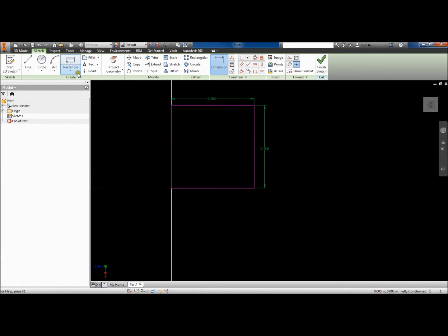The advantage of using the rectangle tool is that if you look at these different pieces, they're already constrained, and that's very nice. When you use a rectangle tool, you have 90 degrees and you have equal sides, so the thing is already locked.